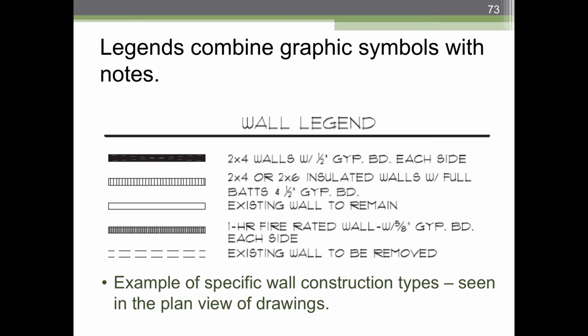Okay. Anyway, some people will get more specific about using hatch patterns to represent wall types. In our case, when we get to the construction drawings phase, so not design development, we will be using one convention, which is solid hatching for new construction, and solid white, I guess you could say, for existing walls.